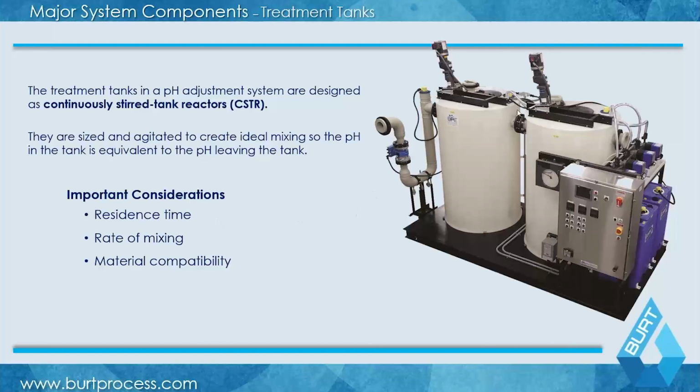So as I mentioned, you can see here, this is a pH neutralization. Residency time, 20 to 30 minutes. There are actually some DEP codes that dictate what they want for residency time. For example, if you're operating in New York City, they want a 15-minute residency time as a minimum, but 20 to 30 is typically the standard in these cases.